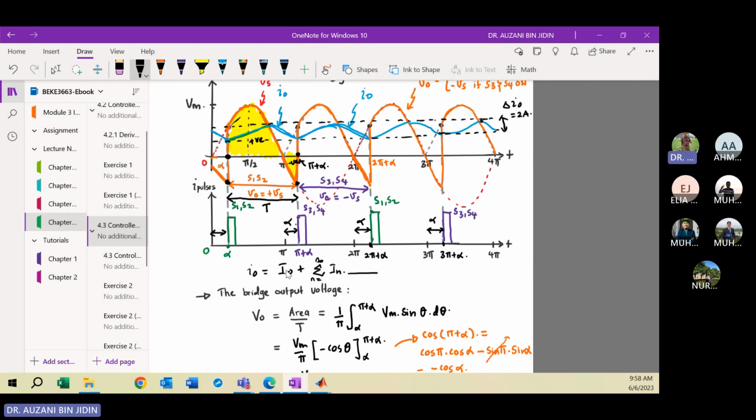You look at the DC current, the blue color. From here you can get the average, the DC component. If you draw the Fourier series frequency spectrum, the DC component is located at 0 Hz. Here is frequency, and here will be your N. So the first component is the DC component, which is located at 0 Hz or N equal to 0.